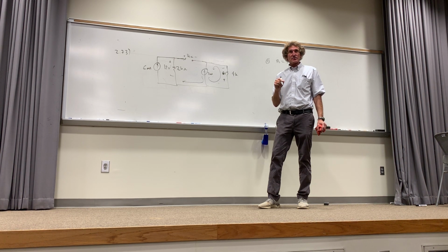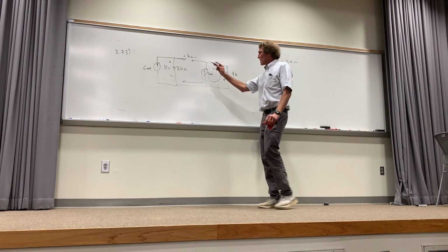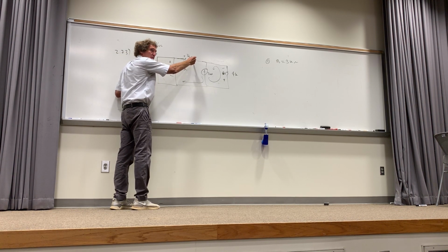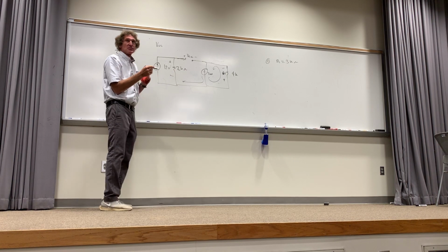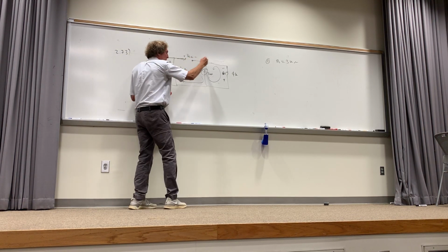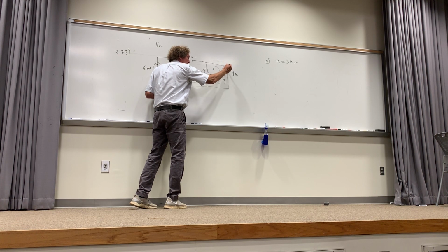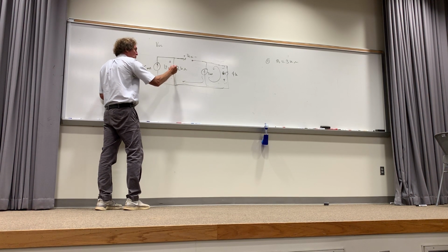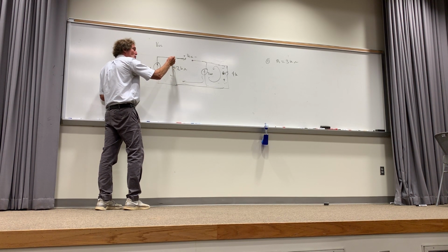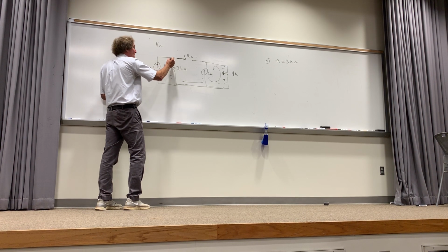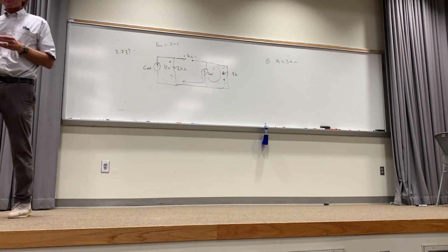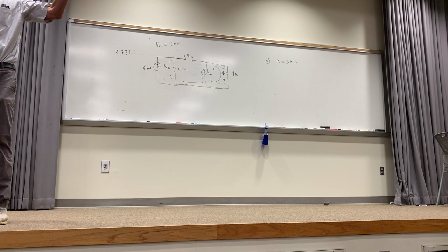I'm going to show you something else to get this open circuit. Be attentive here now. Force yourself to be attentive. This is important. Now, when I want what V open circuit is, what I do is I start at the negative terminal. Remember, you can't sum voltages through a current source. Remember that always. You come here and I come this way. Is this a voltage increase or decrease from this point to this point? Increase of 8 volts. I keep going around, right? How about from this point to this point? Increase of 12. Total is increase of 20 volts. So I've got V open circuit. Everybody with me on that? See what I'm doing? Give me a show of hands if you do.